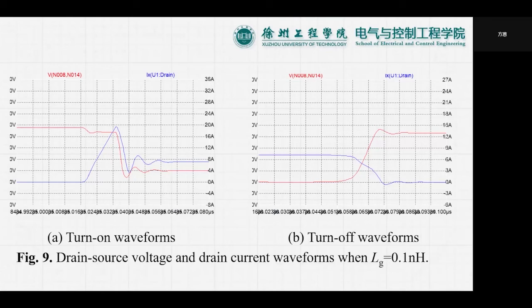The overshoot voltage ratio calculated from the turn-off waveforms is about 7.2%, and for current, it's about 171% when the device is turned on. The turn-off loss is almost 51.585 μJ, and the turn-on loss is about 7.791 μJ.